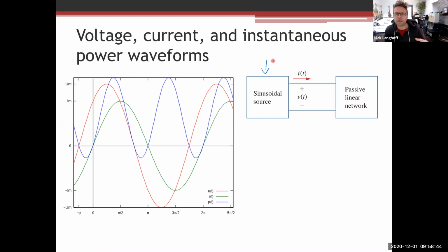But if you use the correct adapters and either the right oscilloscope probes, or you connect it through a suitable transformer, and you isolate the scope directly from the wall voltage, which is up at 120 volts, you'll see that it's actually not entirely sinusoidal. It's close, and our local power providers do the best they can to keep it sinusoidal, but it in fact has all sorts of noise on there.